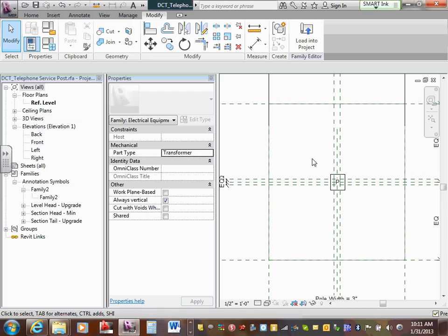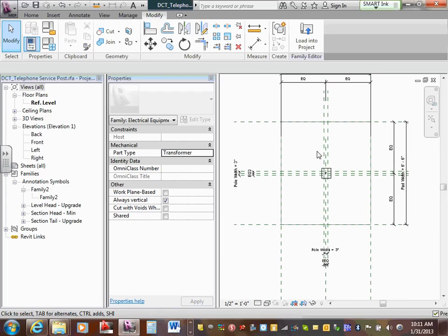Yeah, like down and dirty is, I made reference planes and I constrained them and I made everything locked. You can just create a family by just creating an extrusion and you're done. The family's done, but obviously you can't edit the length, width, or anything in the project. It's just basically a dumb box.